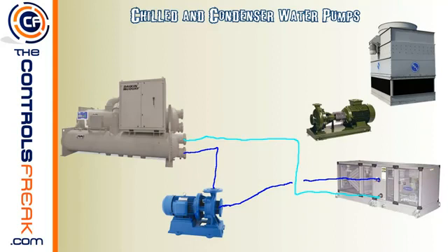The water comes into the chiller, comes out cold, runs through our coils. This could actually branch off and probably hit multiple air handlers all throughout the building. But once they come back, they'll come back on the chill water return. Let's go ahead and label that. This would be the chill water return. And this here is the chilled water supply. And this here would be the big loop. It would go through the pump, through the chiller, and back to the air handlers and so forth.